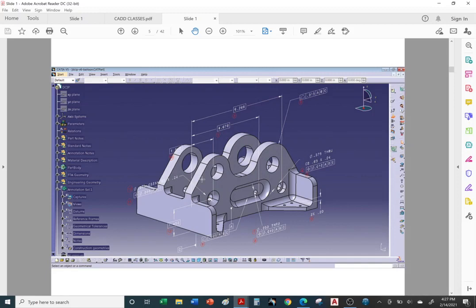How precise? That's tolerancing. That's where we have the GD&T for tolerancing. How much can you be off by? And then they bid on it. Well, how many parts are we going to make? Well, we need 1,000. Okay, so they bid on it. And typically you go with the lowest bid. But sometimes you'll give it to the second lowest bid if they provide better quality and can meet their deadlines. So you don't always have to go with the lowest bidder.